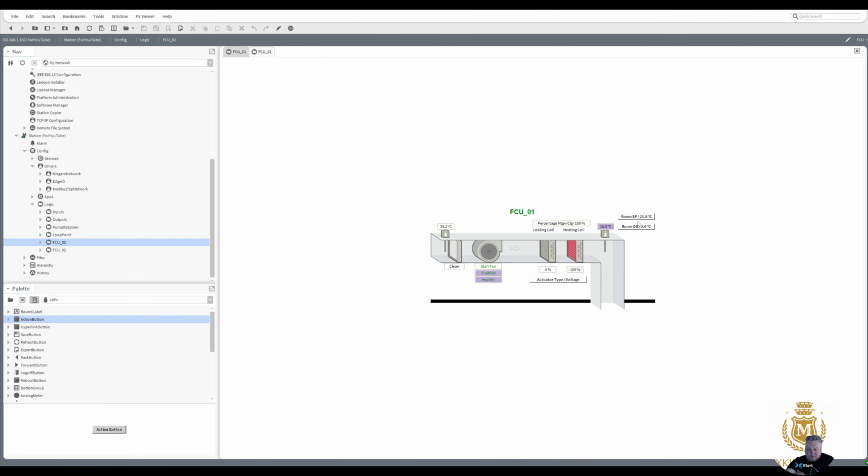Well, the set points are 21, 20, 25 and 2, 0 to 100. Let's put this one to digital. Yeah, that's your analog, that's your digital. So Fan Coil 2 has got digital valves, Fan Coil 1 has got analog valves, and you can adjust the set points.